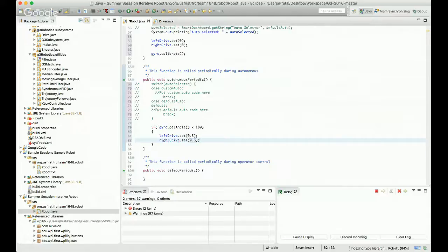If you're trying to do something, it's always better to start slow and speed it up, just so you know what happens. One of the first things that we do when we power on a fully functioning robot and start to download code is give it a really small signal and make sure all your vectors are moving in the correct direction. You don't want vectors to fight against each other, because that could destroy components and stuff like that. So starting slow is always good.